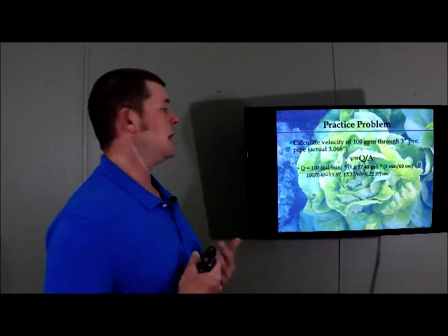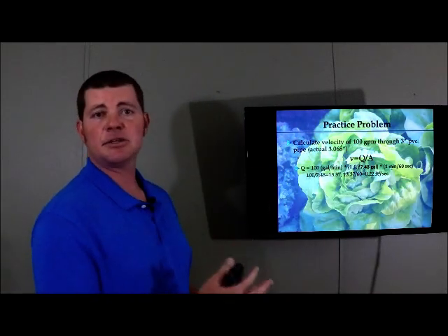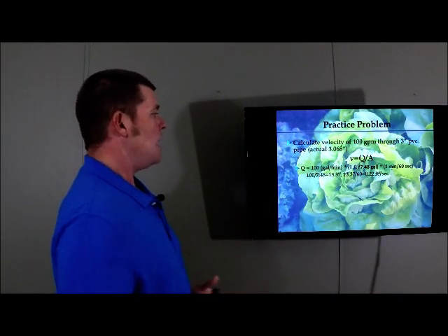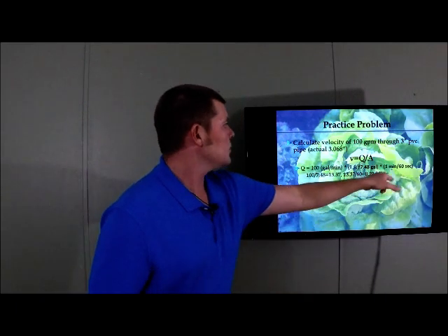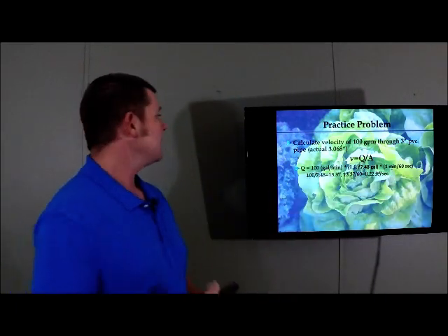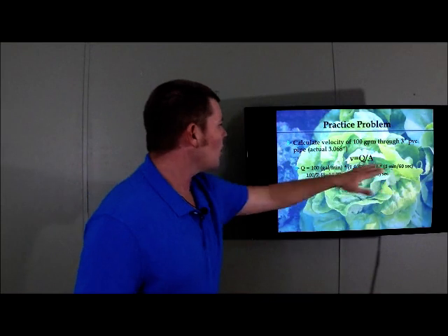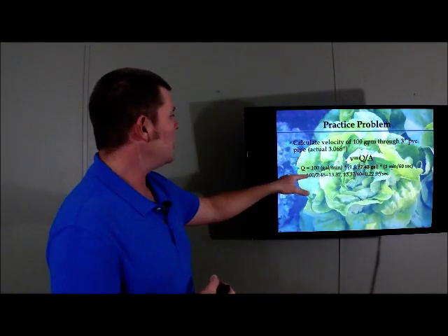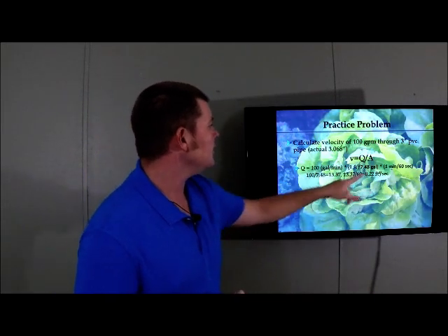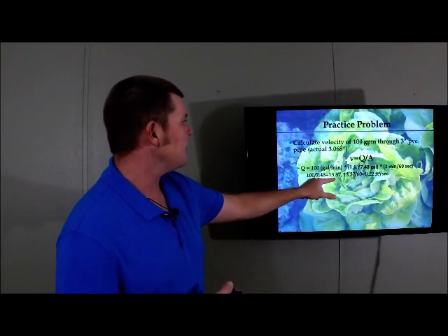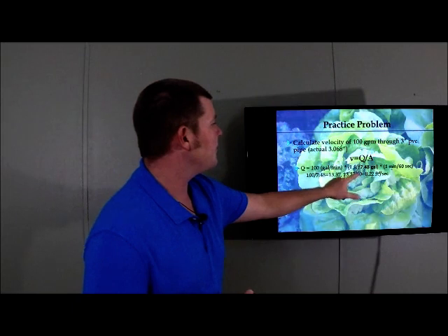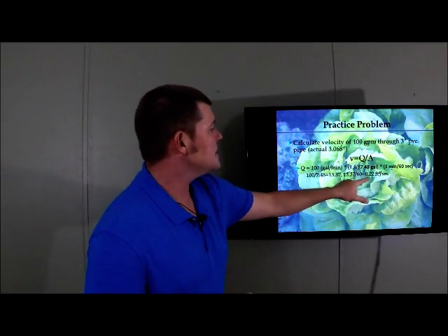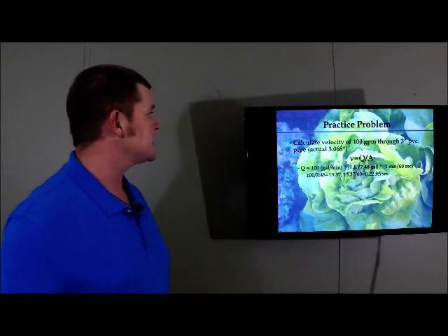So that's just a conversion that's added into this formula to get us the right answer. That's a given. 1 minute equals 60 seconds. That's a given. Okay, so everything's given here. All we needed to do is plug in 100. This is very easy. 100 divided by 7.48 equals 13.37. 13.37 divided by 60 gives us 0.22 cubic feet per second.